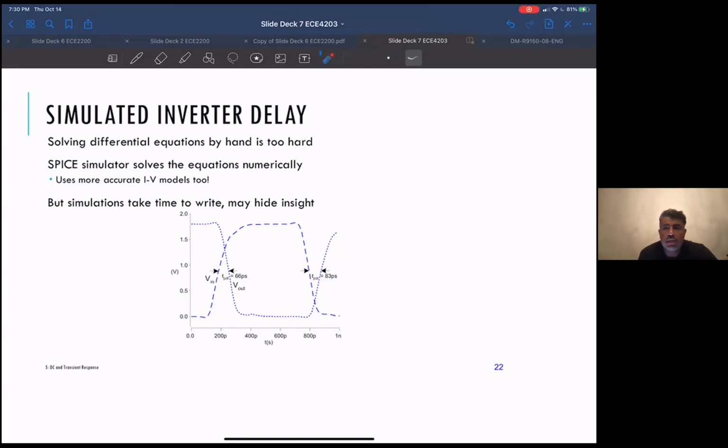What you want to do is a lot of estimations. That's where you're working with Excel sheets, back of the envelope estimations, hand calculations, to make sure you're in the right ballpark. Because if you've already designed your circuits, or you're doing SPICE simulations or logic simulations, by then if you're going down the wrong track, it's bad.